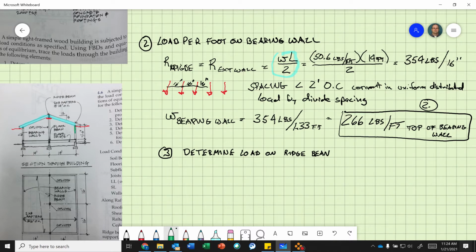so I may have to erase some. So that's the right side rafter, and then I also have another one, right? Because they're uniform. So basically, every 16 inches, I have 2 point loads because there's 2 rafters, this side and this side. So I got to take that point load and multiply times 2 every 16 inches. That is the load on that ridge beam because there's 2 rafters. This only accounts for 1 rafter on that ridge board, but there's 2 because you have the other side.